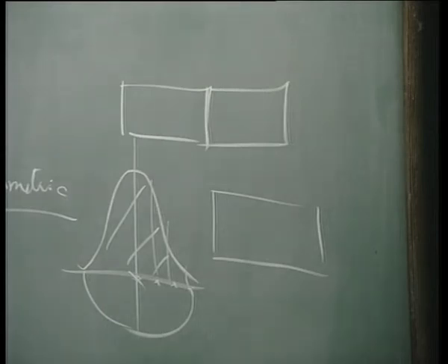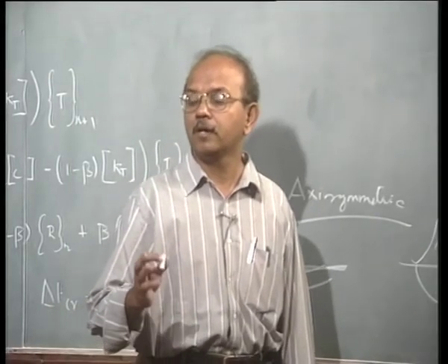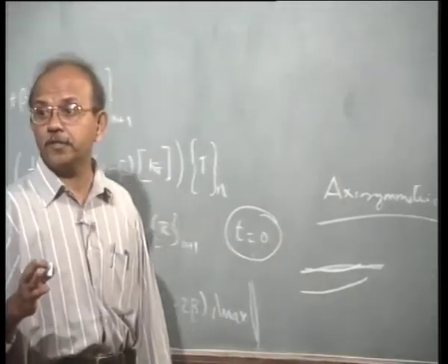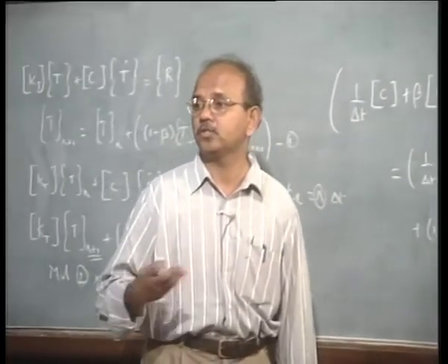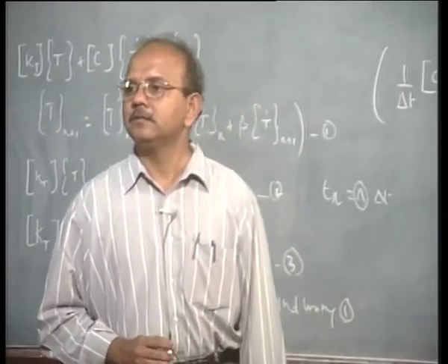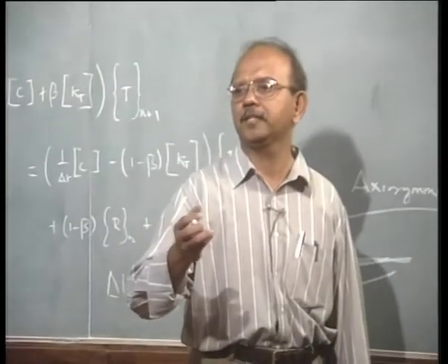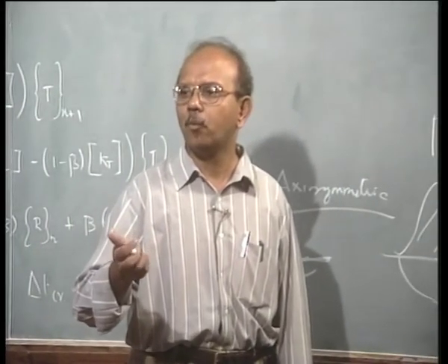Now, what are the assumptions that we make in this pipe for thermal boundary? You want to discuss thermal boundary condition, right? So, what are the things that we make? We assume that there is convection from the surface, both inside as well as outside. Now, inside we know that the heat transfer will not be as efficient as outside. Why?